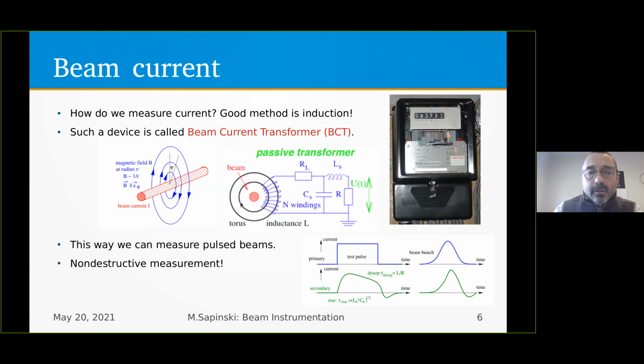Okay, and here you see what is seen in the control room, and I don't remember where it is from. Maybe it is from GSI actually. The point is that here you don't need very fancy electronics for this very basic measurement. You just use a commercial spectrum analyzer. You connect it to your BPM, and maybe in your BPM you need a little bit better amplification of the signal, because usually your spectrum analyzer is in the control room, so it's quite far. But this is the measurement that is done.